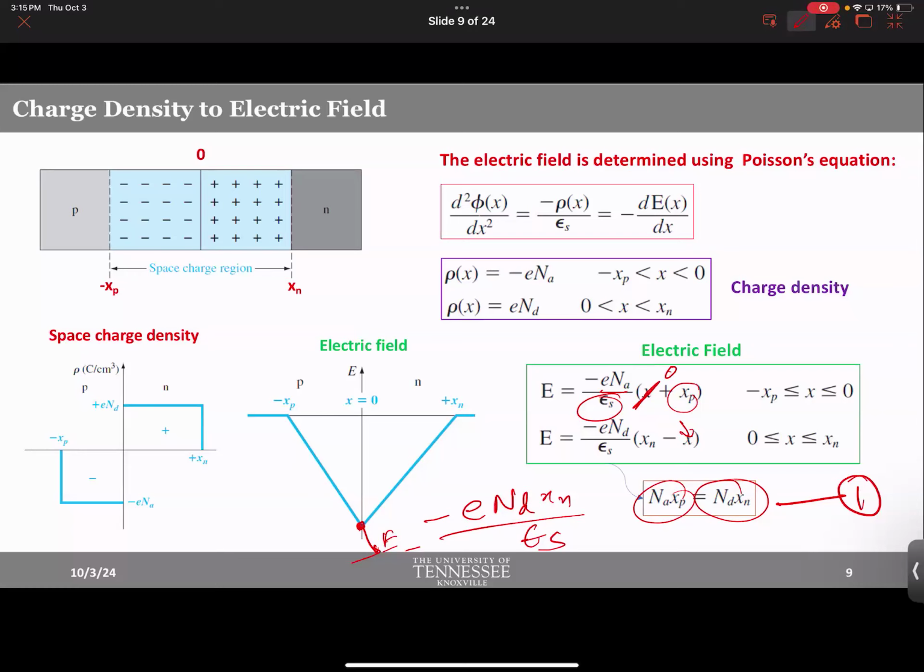Okay. Air is an insulator. It's supposed to not let any electric current flow. But during lightning, you have a current flowing through to the ground, right? So apparently the insulator failed to work. So it broke down, right? When do you have lightning? Whenever there is a high voltage buildup, voltage difference buildup, that's when you have lightning. So electric field is directly related to voltage. Higher electric field represents higher voltage. Okay. So whenever you have a high electric field buildup, there is a higher chance of breaking down.